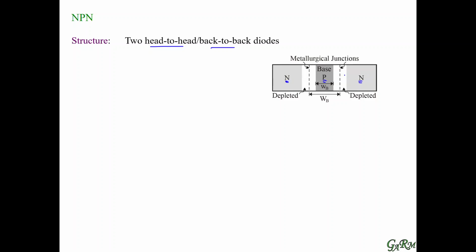Between that junction, the high concentration of electron carriers will tend to diffuse over to regions of lower concentration. And on the left, we also have a high concentration of holes, which will tend to diffuse over to the right. As they diffuse, they vacate a region that we'll call the depletion region. They will continue to diffuse until they build up an electric field that opposes that diffusion action. When it reaches equilibrium, we have a depletion region between every PN junction.